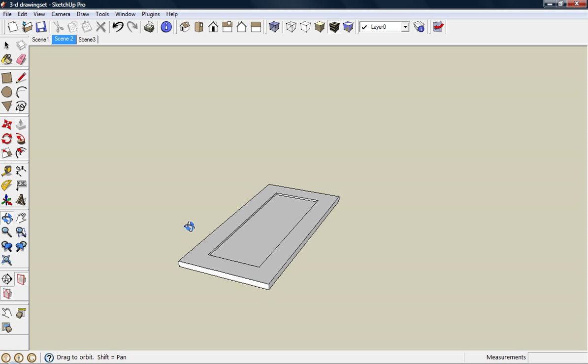I can go further by using offset again. I'll offset that new rectangle that I created. This time we'll offset it, say 1.5 inches. I'll select that new rectangle, and by using the move tool I can now move that rectangle around.